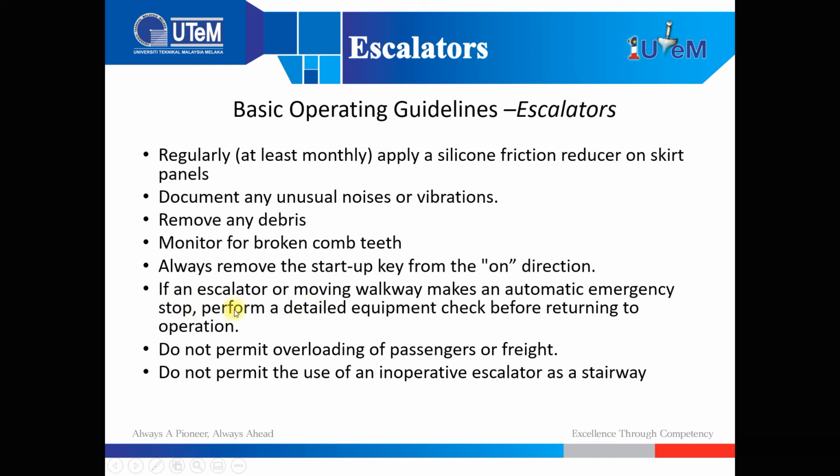Okay. If an escalator or moving walkway makes an automatic emergency stop, perform a detailed equipment check before returning to operation. Because when it automatically turns to the automatic emergency stop, it means something might have happened lah to the escalator or the moving walkway. So we cannot, orang kata apa, take it for granted lah. Must be a detailed equipment check before returning to normal operation lah. And then do not permit overloading of passengers or freight. Do not permit the use of an inoperative escalator as a stairway.